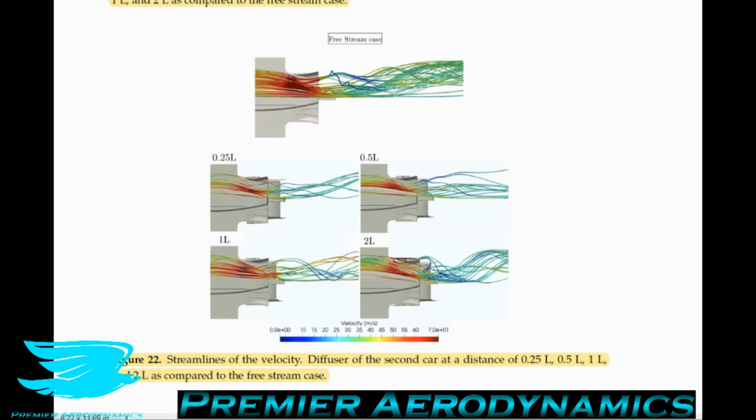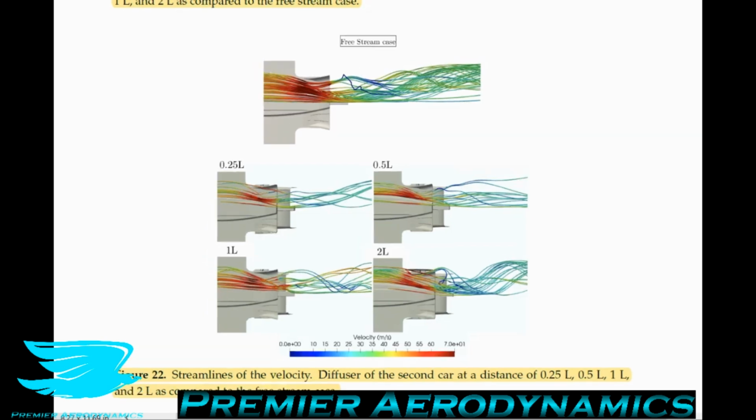The main reason for the massive downforce losses that are reported in Table 9 is that the underbody is noticeably sensitive to underwake flows, as it works closer to the ground than the front wing. This means that the low energy and highly rotational airflow that may not be compressed around this small area, therefore experiencing a massive performance loss, comes in through here. So let's break this down a bit more. I'll zoom in a bit more so we can see.